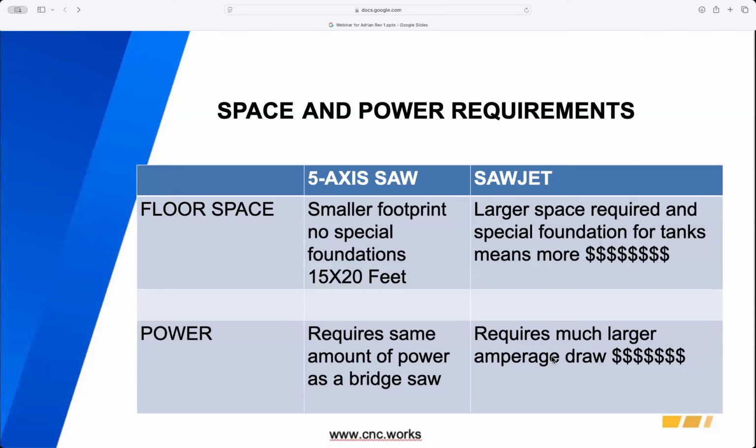Right. And as the garnet makes its way through the intensifier pump, are there impellers or things like that that get worn down because of the garnet? Actually, it's not added at the pump. The garnet's added at the tip. It has a hopper and it pulls it through a line, which then introduces it into the water right before it hits the tip. But that garnet does cut the tip because it's a lot of water and a lot of pressure. So that leads to the maintenance as well, but we'll talk about that more in a little bit. Okay. Anything else people should know about floor space or power requirements? That's about all I have for now.